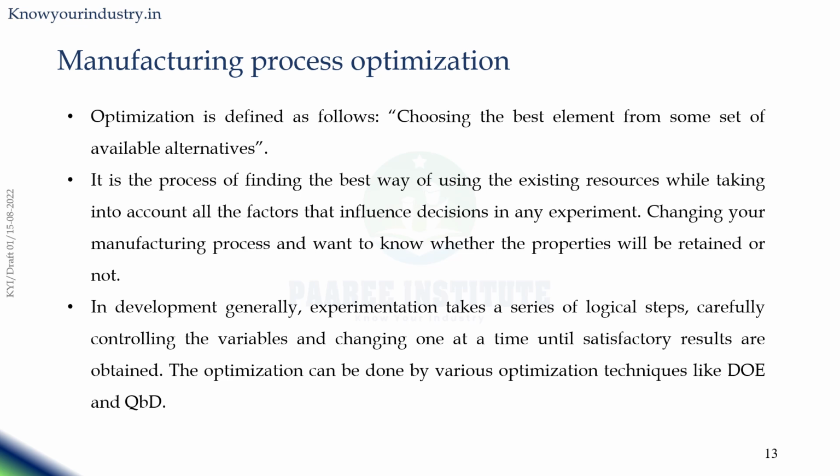And next, manufacturing process optimization. Why does it have to be done? Because every manufacturing condition has to be optimized. Each manufacturing process has to be optimized. If you are preparing a granulation, the granulation time, your addition time, and if you are making a top spray granulation, you have to control your blower speed and your spraying time. Everything has to be optimized.